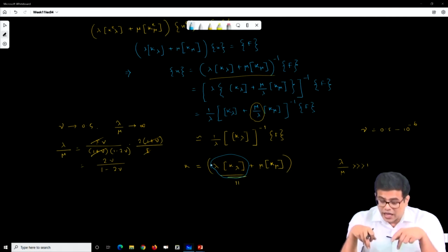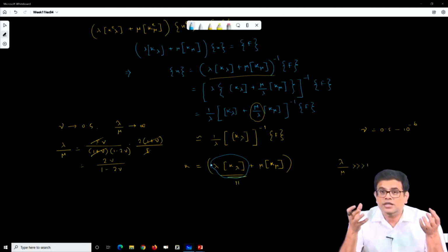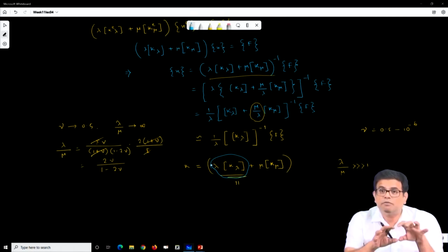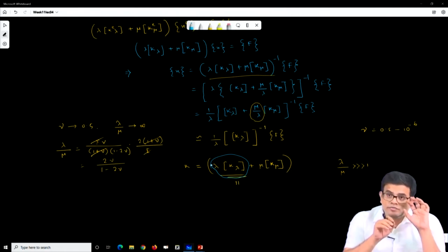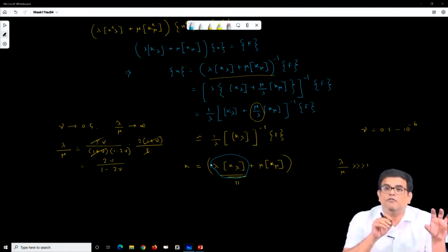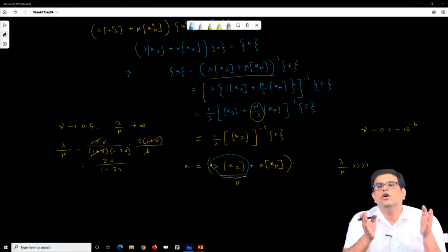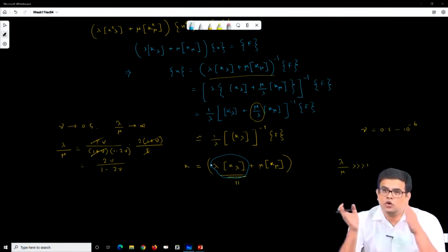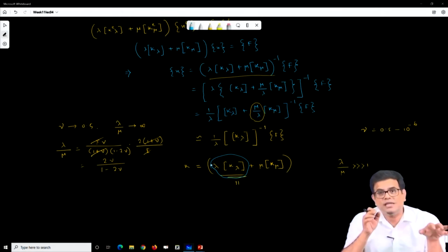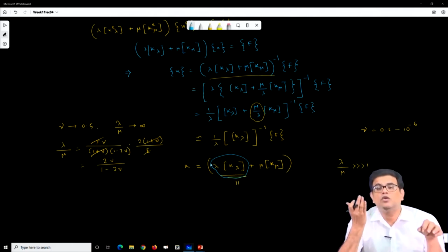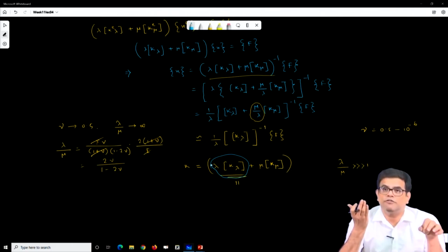While in selective reduced integration, we are suppressing a particular type of deformation. For instance, here the volumetric deformation, which we know will be 0 for Poisson's ratio close to 0.5, we can suppress, and we can bring out the deviatoric part of the deformation.